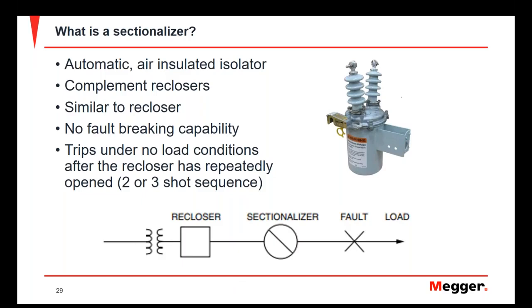So DC high-speed circuit breakers are typically found in railway applications or traction power substations. They're also found in some DC vehicular applications such as DC haul trucks. The railway application has a rectifier system that supplies the system, and then the DC circuit breakers will operate to protect the system.